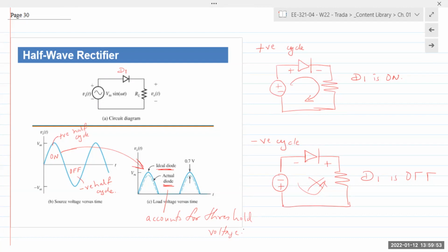Right? A half wave rectifier only rectifies half the wave. Now you may ask, this doesn't look like DC. And you'd be correct. It doesn't look like DC, but it's at least going in one positive direction. It's not reversing like AC. It only has positive peaks, right? So for a device, sure, the voltage is interrupted and it's very inefficient because just a little bit of the actual signal is coming through. So it seems very highly inefficient, right? And that is absolutely correct. That's why this model is not very preferable.